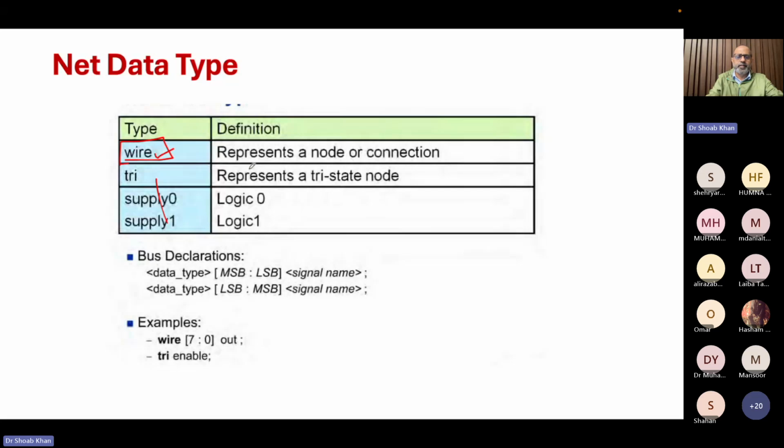So you've got to have a wire. A wire is a type of variable, like wire [7:0] output, so output is a wire type of variable. This is the type of variable where you have some inputs and you calculate from these inputs. Anything that you don't want anybody to change is a wire. A wire assignment can only happen once on a wire.